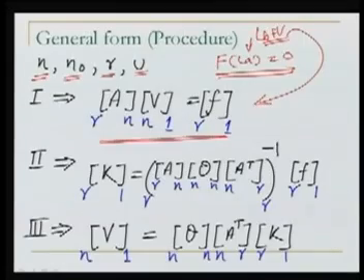The important thing is to look in that particular problem for the independent conditions, and those independent conditions should be equal to the redundancy, and we have to write those condition equations. This is very important, the very first step of the problem. We are solving simple problems here, but sometimes problems could be very complex.